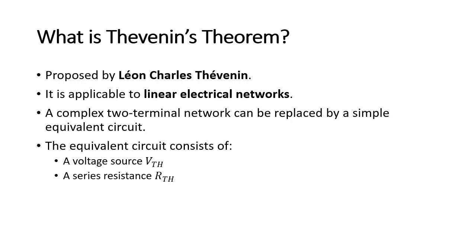For the complicated circuit, we can find the values of the Thevenin's resistance and the Thevenin's voltage. By simplifying that, we can draw the Thevenin's equivalent circuit which consists of a Thevenin's voltage VTH, Thevenin's resistance RTH and a load resistance RL.